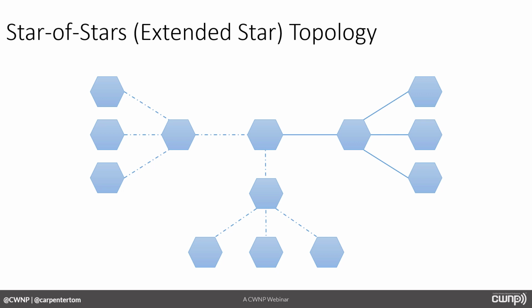I'm not going to go to that level of depth today, but know that LoRa refers to that local link between a sensor or an actuator or another type of IoT device and the LoRaWAN gateway. That's where the LoRa protocol is used. The LoRa protocol is not typically used between the gateway and then the internet or the rest of your network.